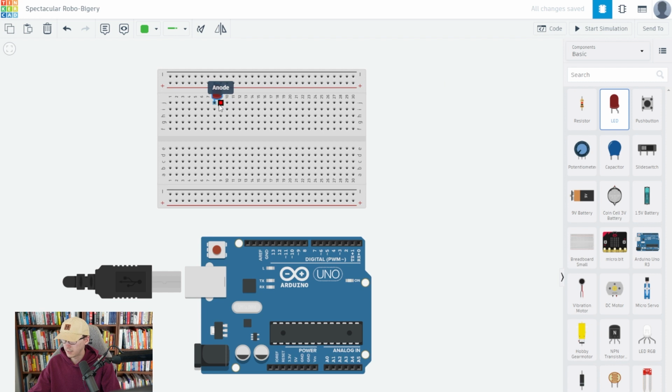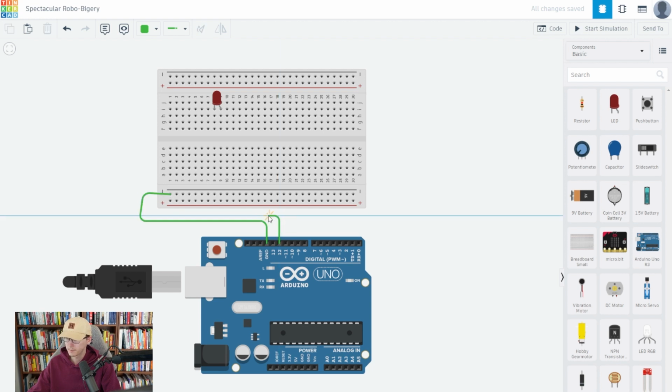So we need an LED. This is our first attempt at actually turning on a real LED. It's pretty cool. It's not using the board one anymore. We're expanding outwards. So what we need to set up is a pin to ground. All of our circuits need to be a complete circuit that follow a flow like that. So then the next one, we're going to be connecting this to pin 12.